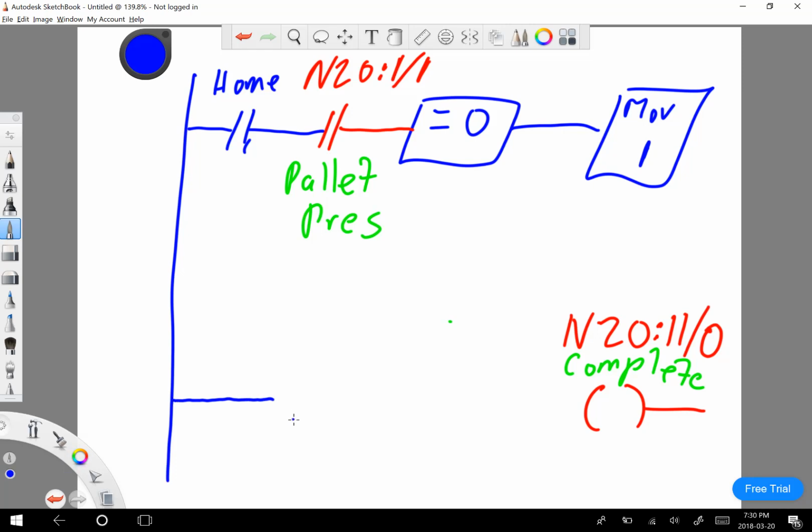What I've been doing is, when I'm at one of the last steps, if I'm equal to step 7 or step 8, whatever one of those final steps is, I've been doing it on station 1 there, basically when we're moving up out of the way and we're about to do our return motion. So if we're equal to step 8, turn that bit on, basically after we drop the part and we're ready to be finished. That's what we can do there. And that is basically what we need to do to interlock.